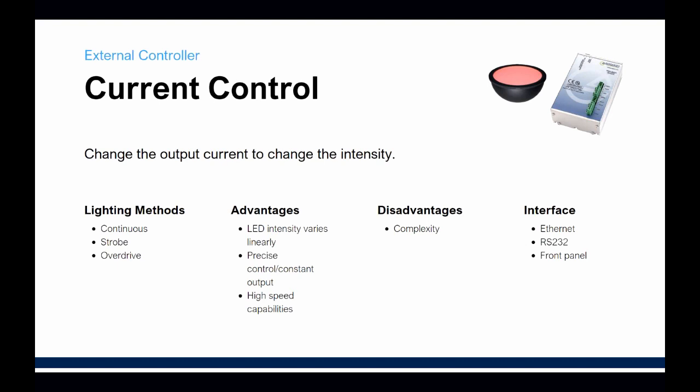The disadvantage of this one, I put complexity, and that's true for Gardasoft. It's also kind of true for pulse width modulation, or even the voltage controller, by adding another component into the lighting. It just makes it a little more complicated versus just having an internal driver. But another interface that you can get with Gardasoft, it's one of the 3. It's either Ethernet, RS-232, or possibly a front panel option.